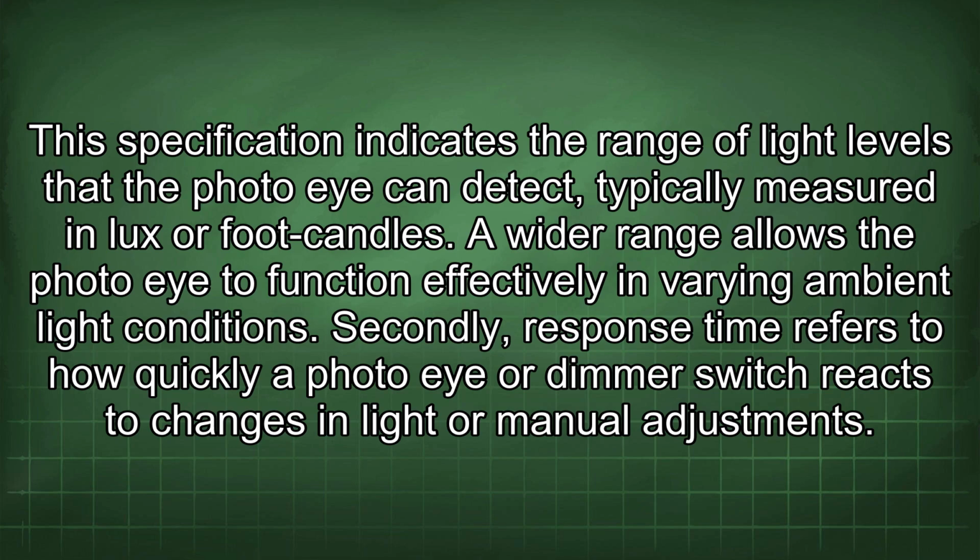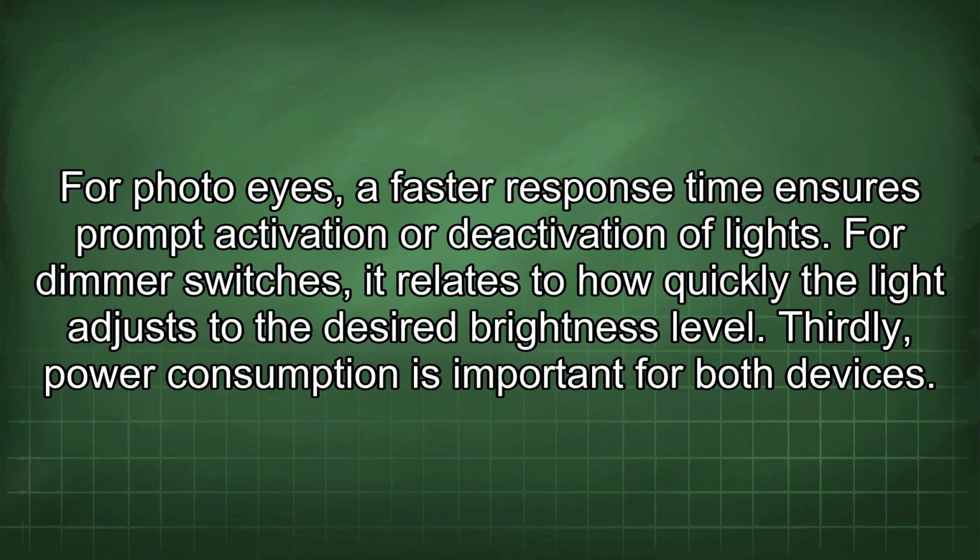Secondly, response time refers to how quickly a photo eye or dimmer switch reacts to changes in light or manual adjustments. For photo eyes, a faster response time ensures prompt activation or deactivation of lights. For dimmer switches, it relates to how quickly the light adjusts to the desired brightness level.